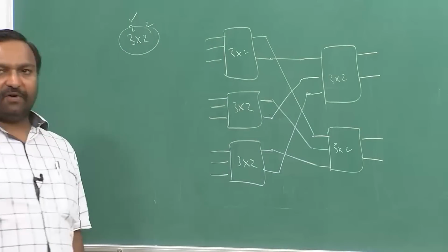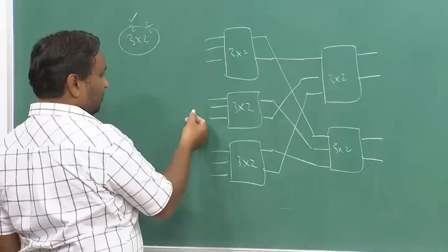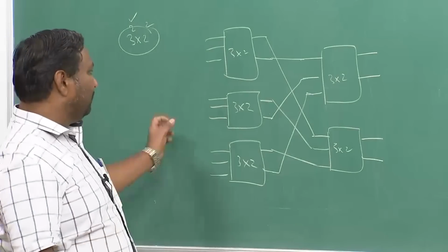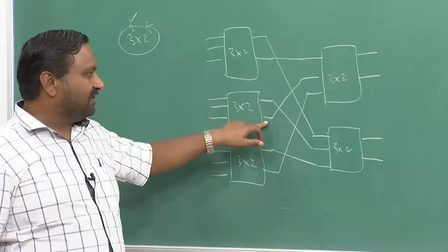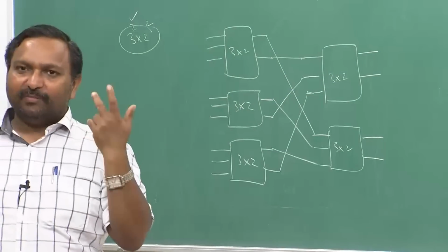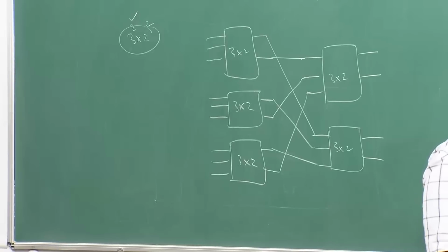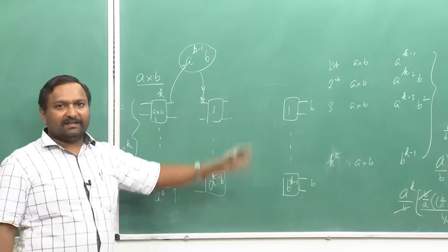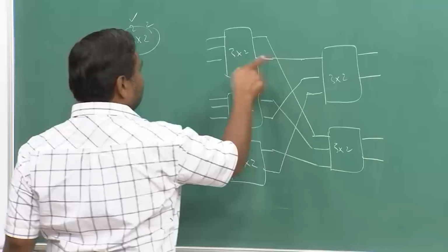So this should be a self routing switch. You put from anywhere. Now, the kind of address which your tag will be putting will be either 0 or 1. So the first bit will be 0 or 1, the second will be 0 or 1. So it is basically 2 digits, both of them binary numbers. So if it is an a by b switch, I will be using k b-ary digits to identify the address of the outgoing port. In this case there will be 2 binary bits.